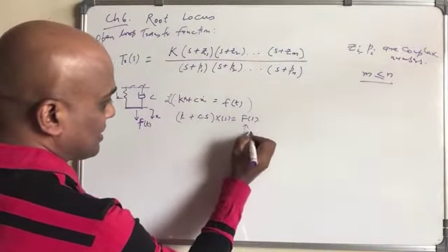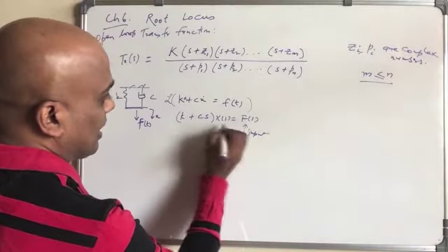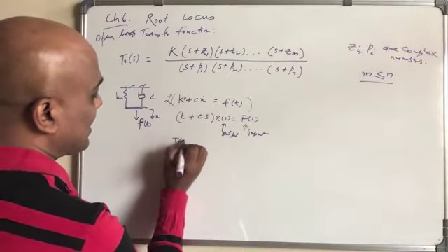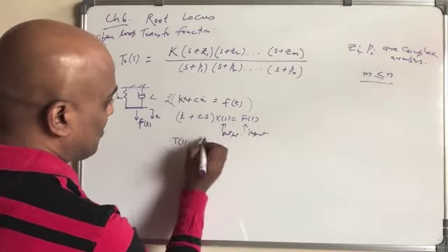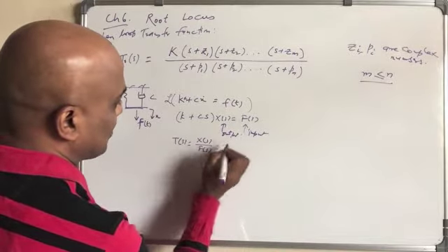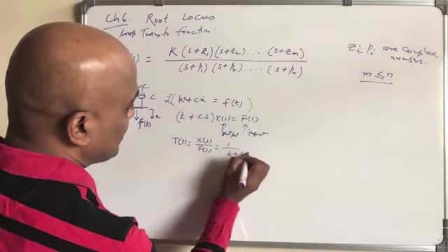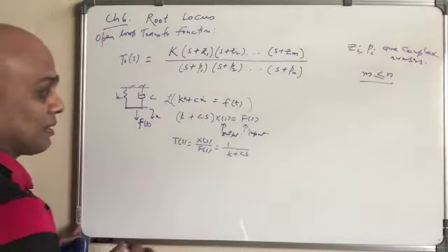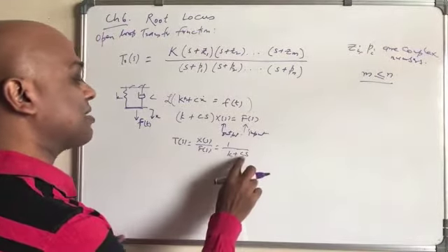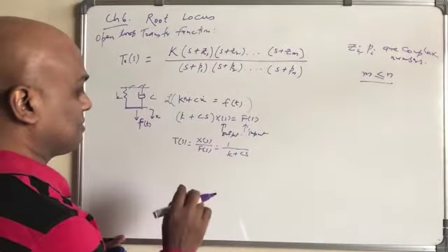Now if you take F as input and x as output, the transfer function X(s) over F(s) equals 1 over (K plus Cs). Hence you see that the denominator polynomial is of higher order than the numerator.